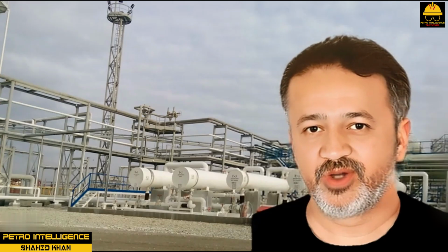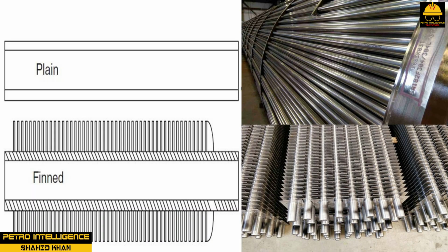Tubes. Tubes on shell and tube heat exchangers can be plain or finned, as shown in the picture. Fins provide more surface area and allow greater heat transfer to take place. Fins can be located externally or internally. Although plain tubes are more commonly used in fabrication, the enhanced features of the fin tube are starting to make an impact on new design engineers.